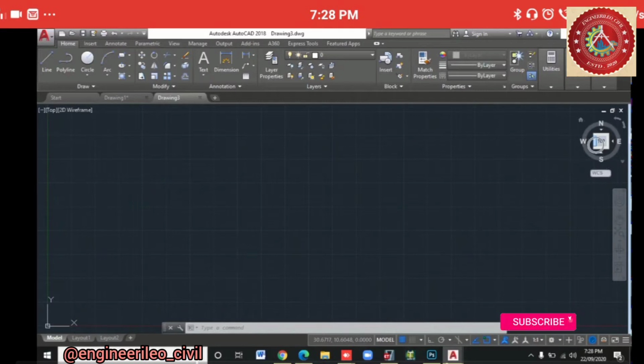Here you can see something. This is the WCS. You can change the direction from here, like if you want to view from north, east, west or south, or view the top, bottom and side views in 3D. You might see the column over here. This is grid mode, which means to display the grid or not. If I tap on this, the grid will disappear. Again if I tap on this, the grid will start appearing.